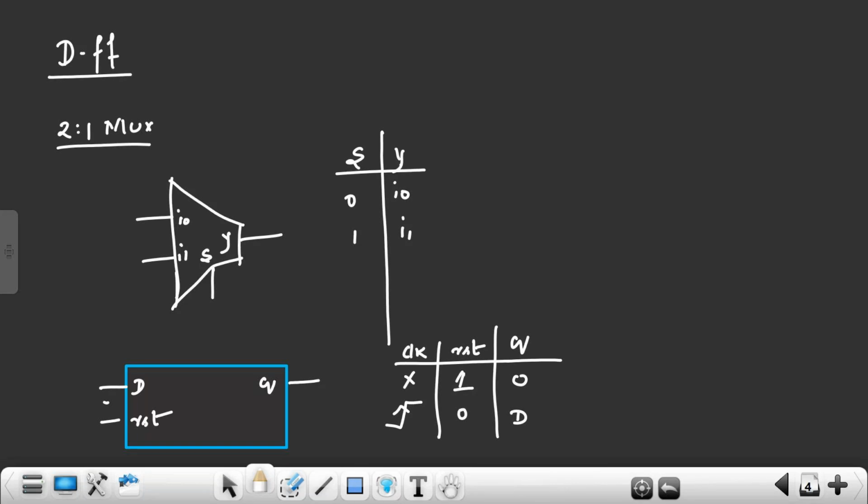Simple, it is. But if I ask you to tell me the internal structure of a D flip-flop, how many can tell me? So writing the behavior of a circuit is very easy compared to structural form. Correct? The designer's role is to write in the behavioral form. Internal algorithms convert it into gate form. We RTL design engineers write in the behavioral form.